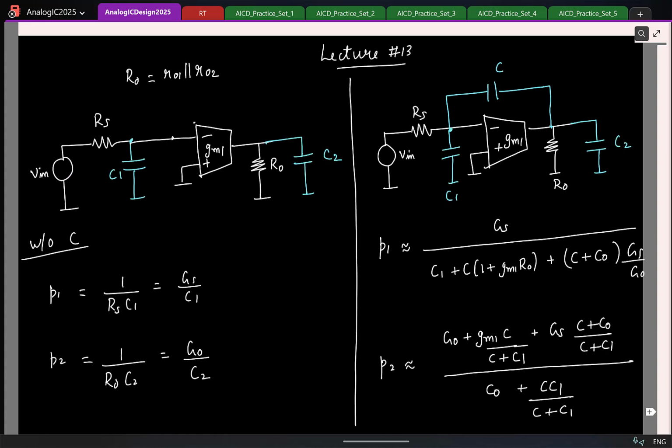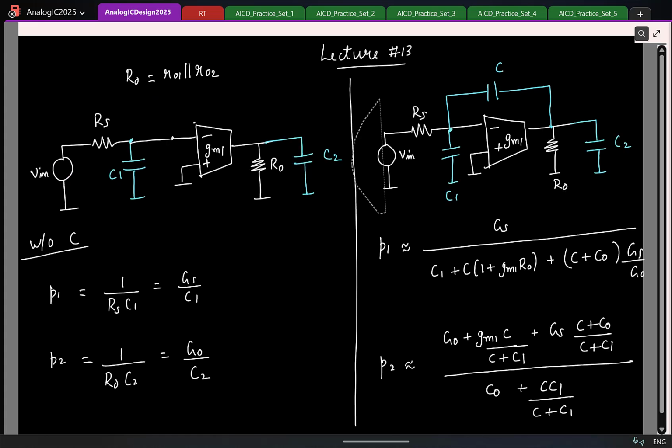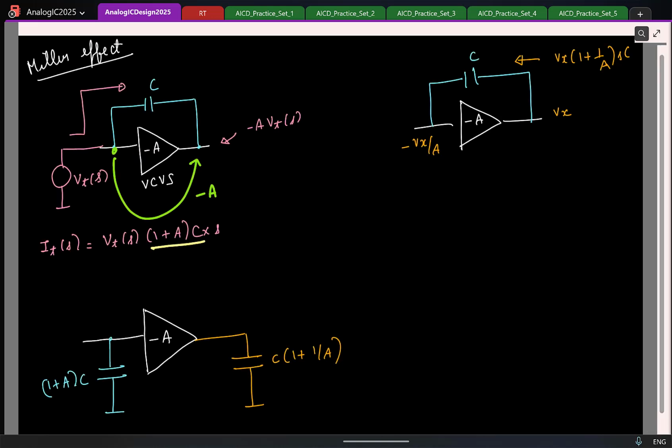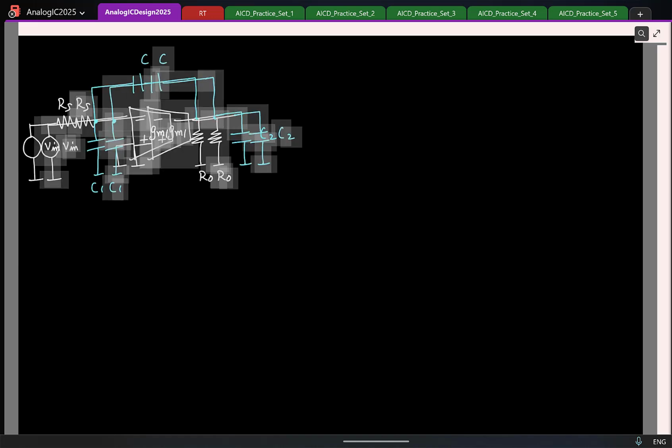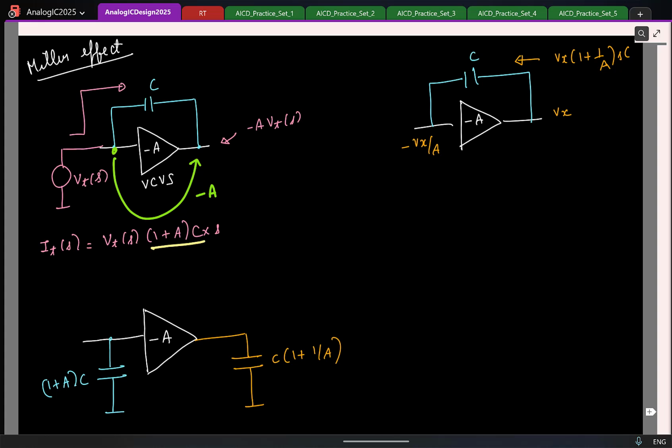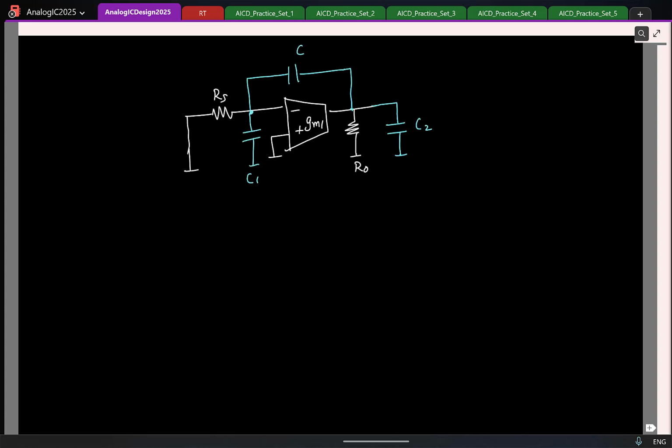But fortunately or unfortunately, we are not dealing with a voltage controlled voltage source here. What kind of control source are we looking at? Voltage controlled current source. Again, we are looking at the pole location, so I can discard the input. Okay. So this is a voltage controlled current source. So if I were to use this result we saw, I need to find the exact voltage gain from the input to the output node, which means here I need to know the exact voltage gain from this node. I will make some space, hold on.